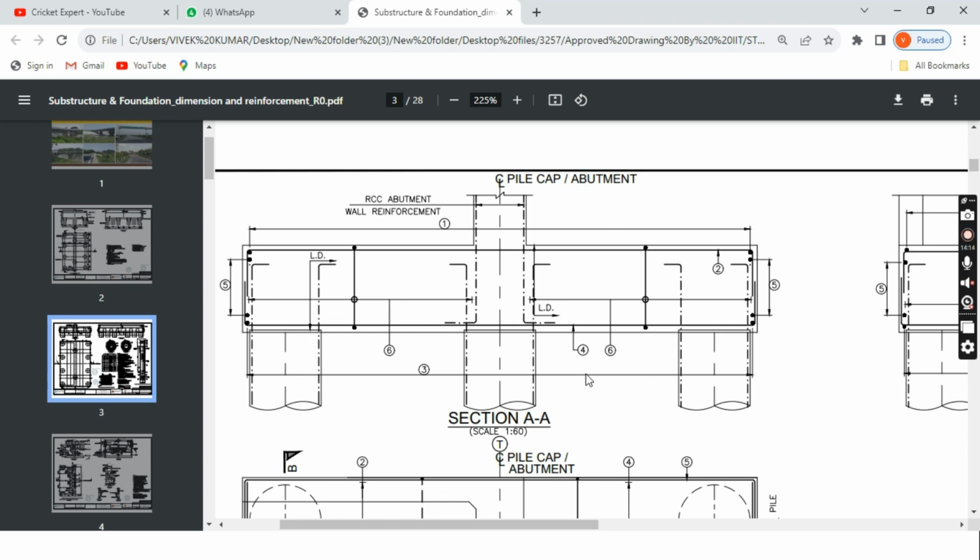Some other bars are also there. So you have to give something like this. As per the height they are lapping some portion here. So you have to lap here at least 300 mm, as per my drawing, means 150 each side, 150 from center to this side and this side. Okay, so as per the requirement I have prepared my bar bending schedule.